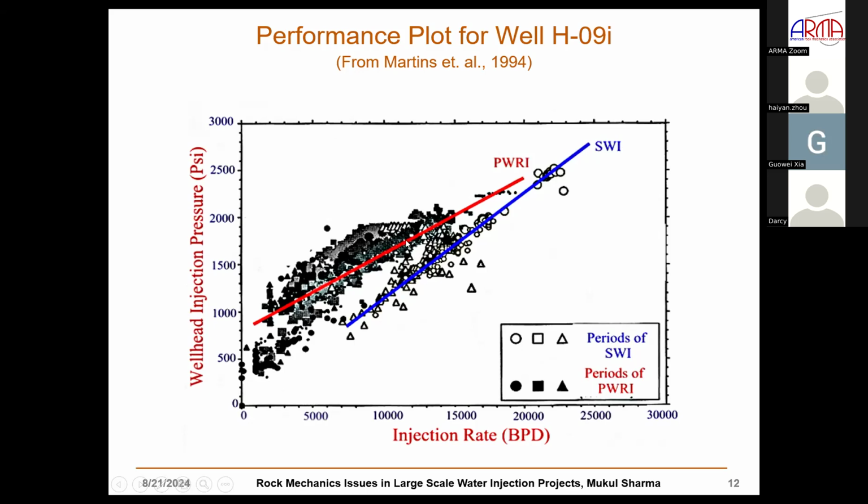And so you get a huge difference in injection pressures, primarily related to the temperature of these two fluids. So this is entirely related to the thermoelastic stresses that are created as a result of injecting cold seawater as opposed to warmer produced water. So clearly, under fracturing conditions, when you have injection-induced fractures, you tend to get a significant change in the injection pressures associated with the thermal stresses that you can get.